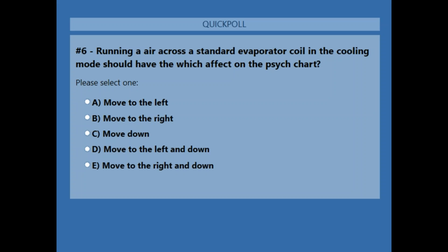Conversely, if I am adding humidity to a space, that's typically done in projects in the winter, like at a house or a library. So if I have a humidifier adding humidity, usually we would start with warm air, because it is in fact easier to absorb the moisture into the air. And I am in a heating mode in those scenarios, so I'd rather have the warm water to start with. I'm not trying to cool.